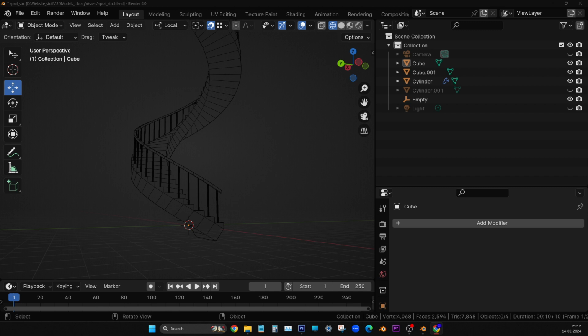Yeah, okay. You are in edit mode. You have to go to object mode and then come to the selection. That is okay. In that case, you didn't name it, no. So in that case, you can visually select in the 3D viewport only.